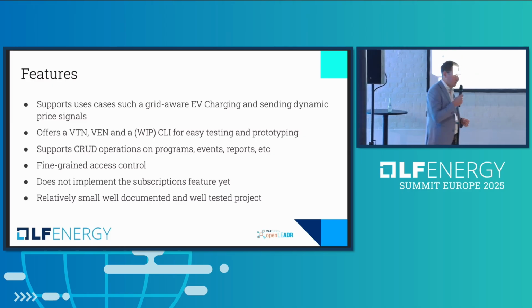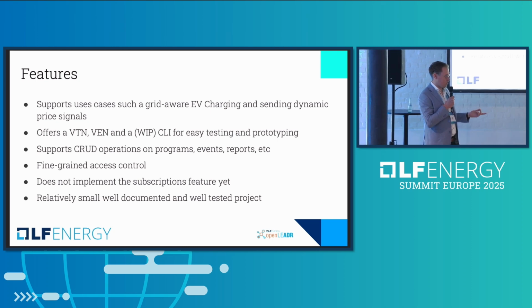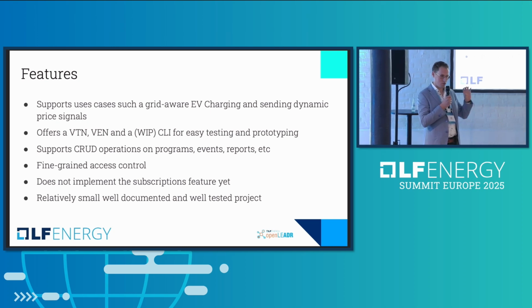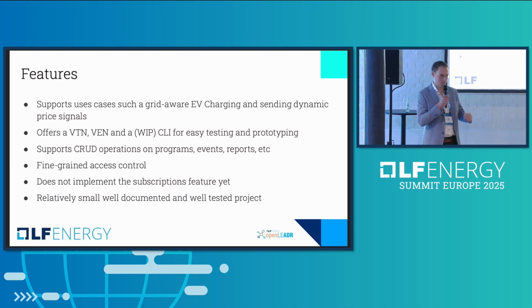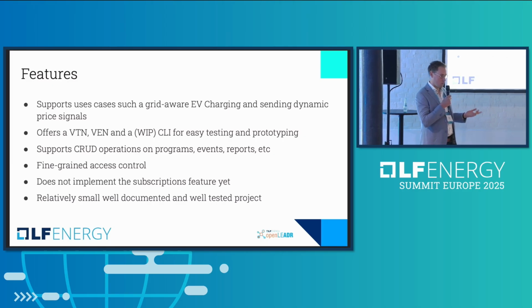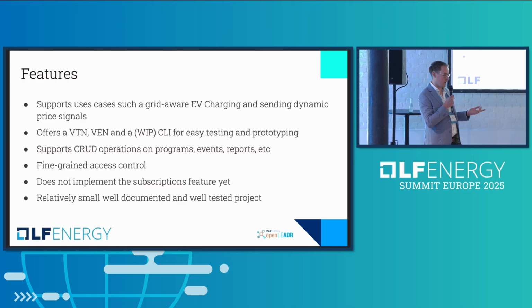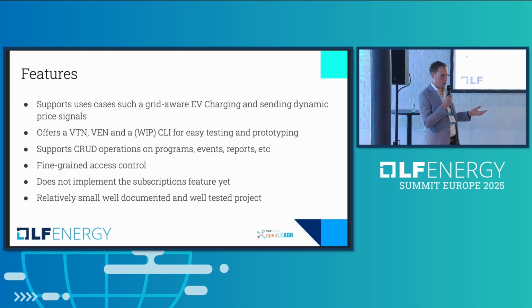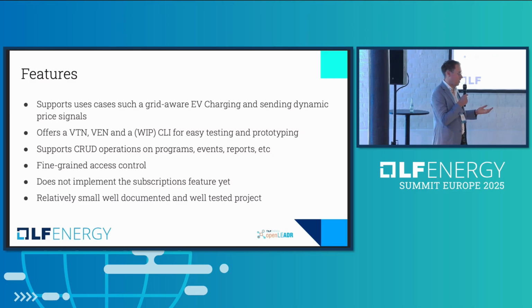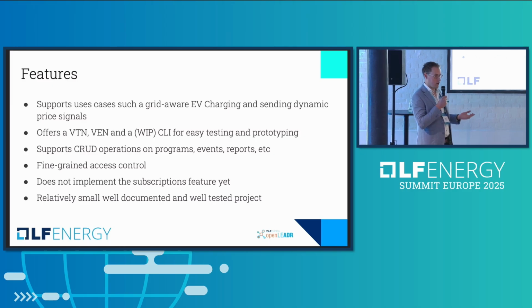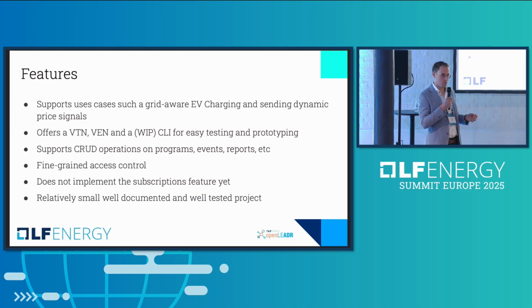So what we offer there is, together with Tweede Golf, we built a very stable VTN, so a server component for OpenADR communication that the DSOs can actually adopt. In there are also the Rust building blocks for a VEN, so a client implementation. But since OpenADR 3.0 is built on HTTP API principles, so CRUD, you can also implement the client in another language if you would want, but I think it's an easy starting point to just use what we built together.